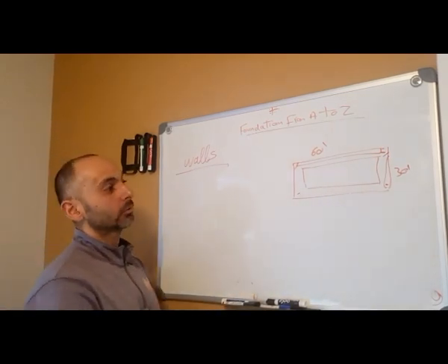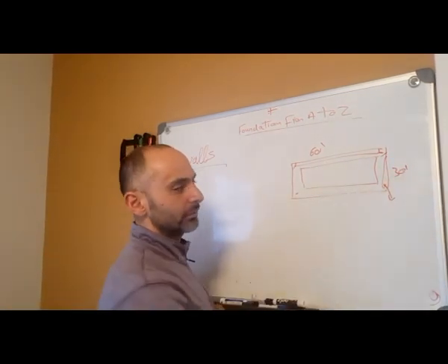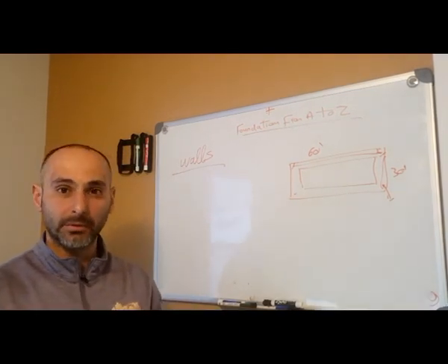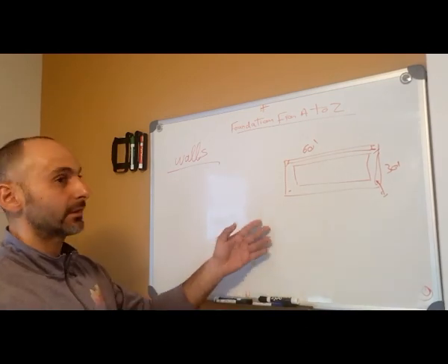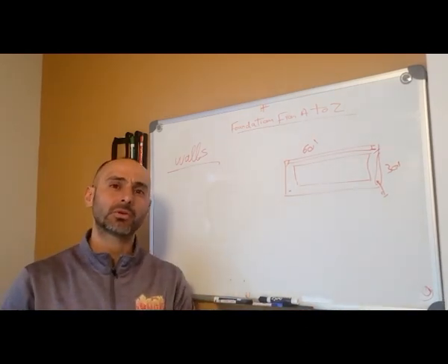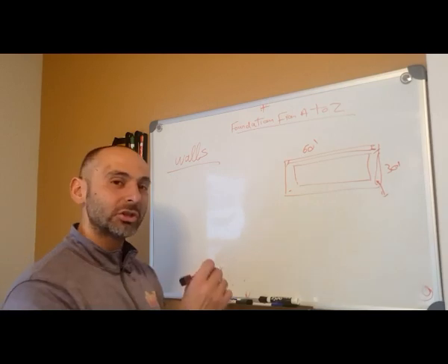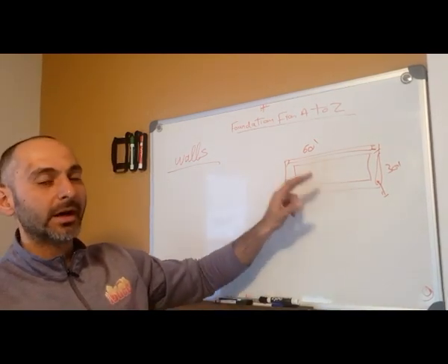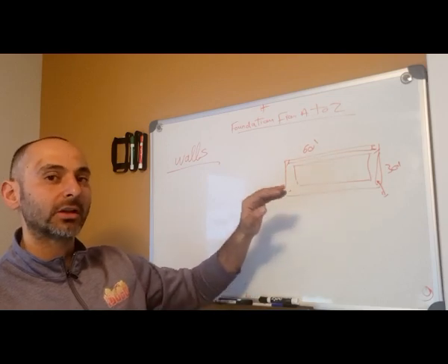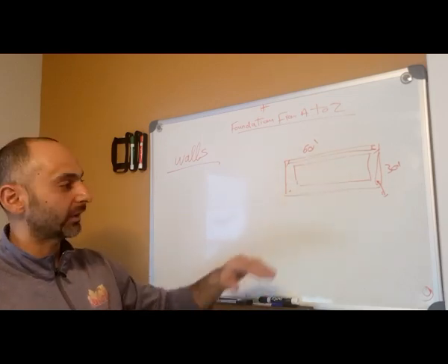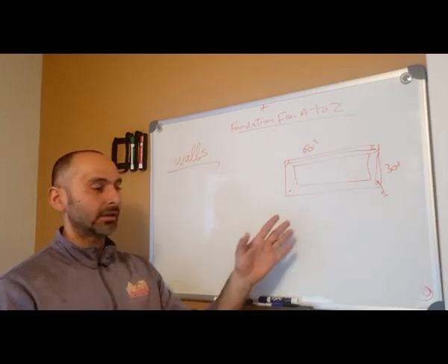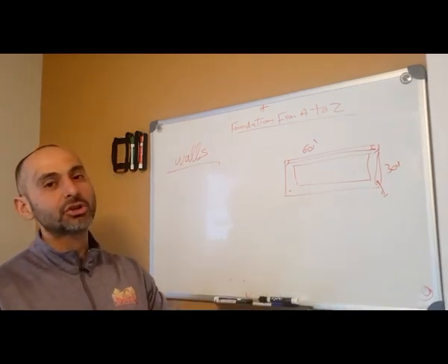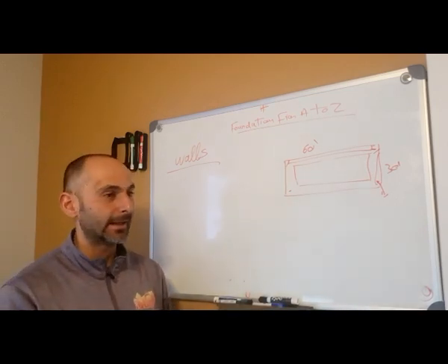Also ask him to shoot. He's already there with the equipment, so it's not going to cost him anything. Ask him to give you the elevation on one of the points so you can check against the numbers you already have with your contractor. Make sure you're at the right elevation, because you have one more chance here to fix the wall. If your contractor built it higher, you can cut the walls or adjust the wall height. If the contractor did it lower, you can add. This is your mason's problem; he has to fix it. But you have one more chance before you build the walls.